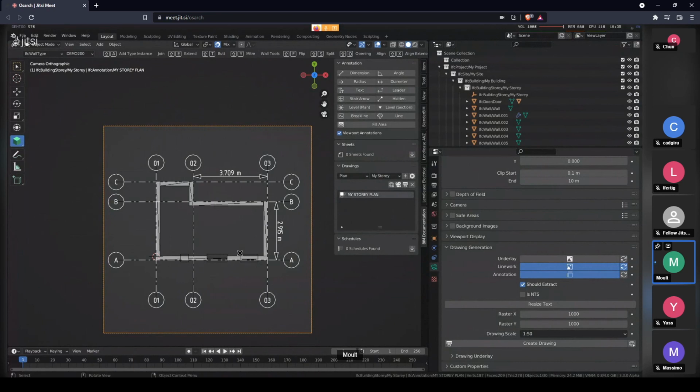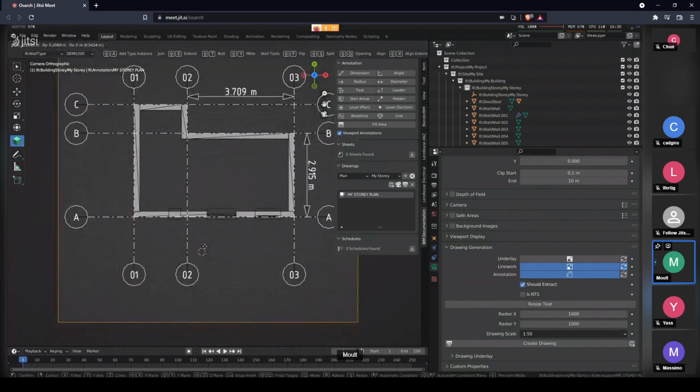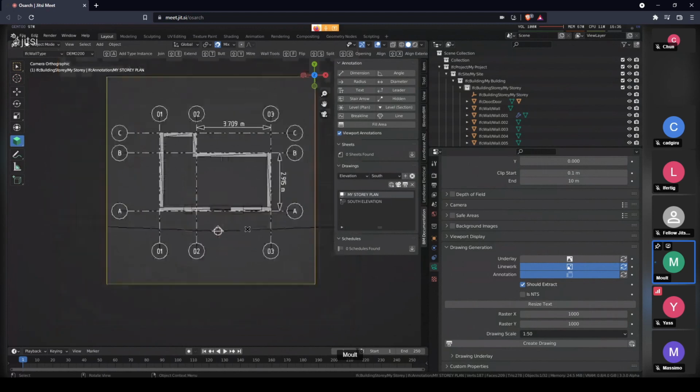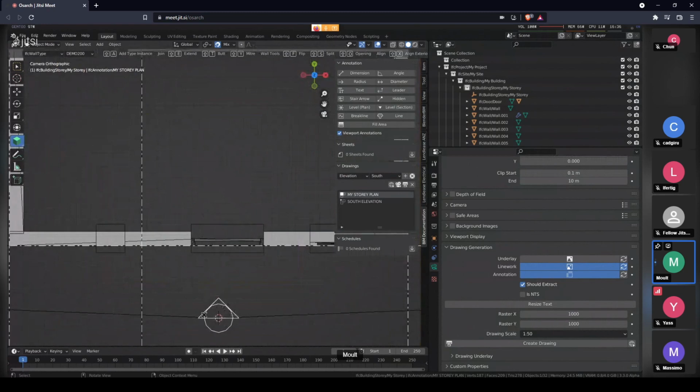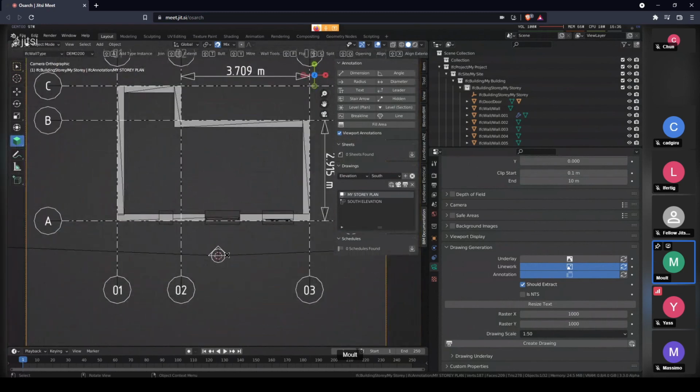Now let's say I want to create a new elevation somewhere over here. I'll place my 3D cursor over here, and I'll choose elevation, and we'll say this is going to be a south elevation. Is that right? Yes, this is the building's south elevation, which means it points north. Okay, so I'll press plus, and you can see we automatically have our elevation symbol. Currently, you don't see the number of the elevation in there. That's okay. We'll talk about sheets and numbers later on, but you can see my elevation symbol is there.